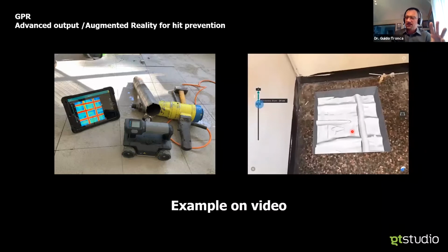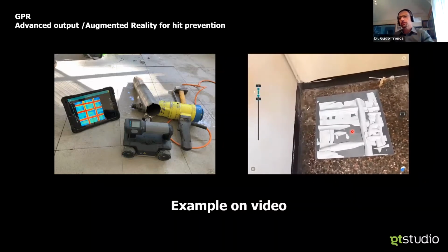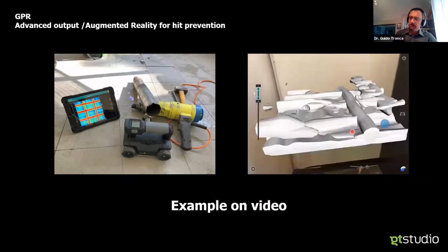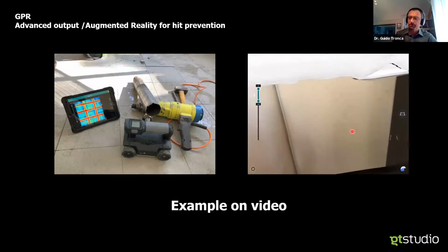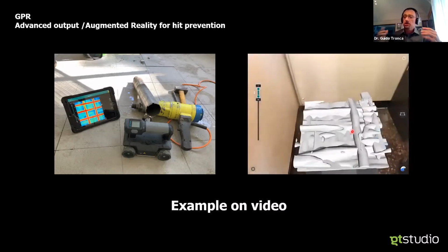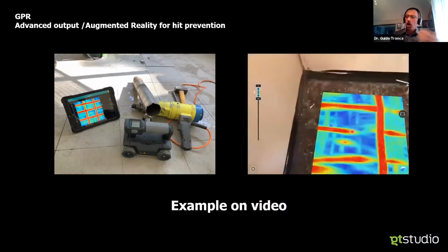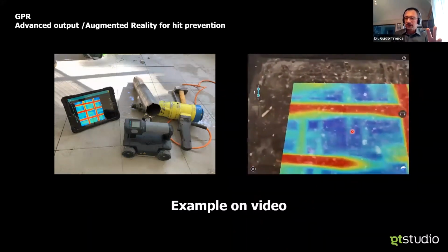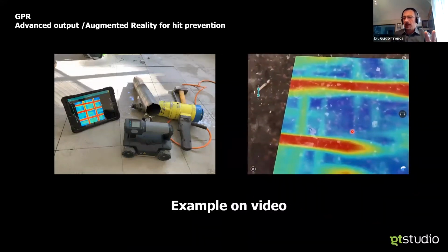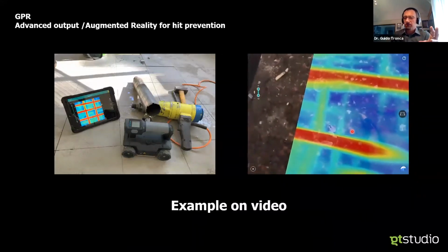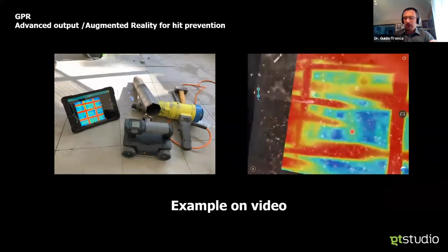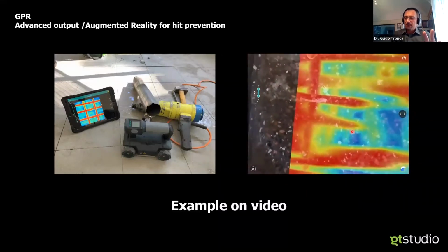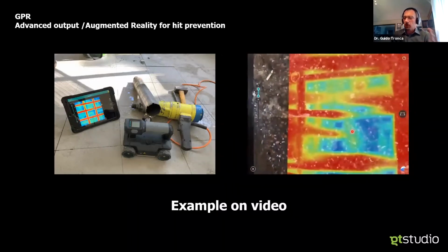But in this case, it wasn't crucial to estimate all the rebars and the exact reinforcement, but basically to avoid those. So let's collect all the scans that we need. Let's focus on the surface itself. Every strong reflector can be assumed to be a steel rebar, and within a reasonable time, I can estimate the right spot to drill a core.